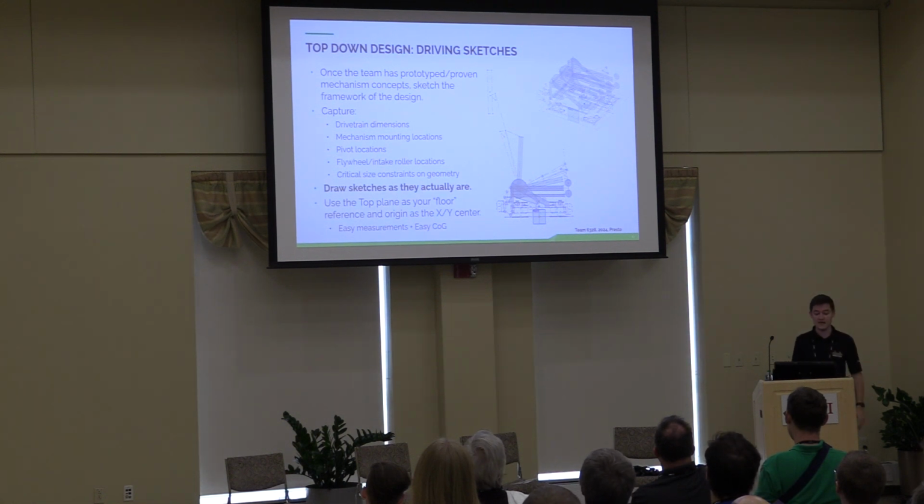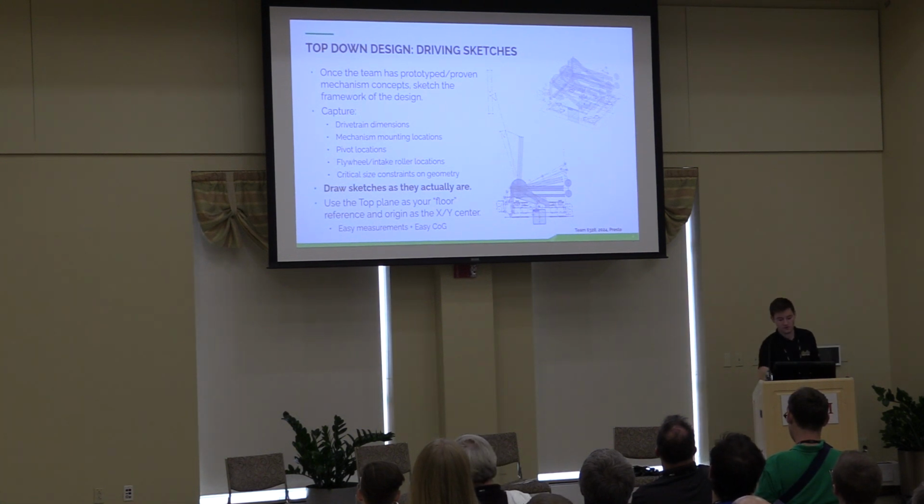I've actually started renaming it from top to floor, so you can just rename the default sketches, the default planes, and use that as the bottom. For example, you can see, and Susan did that as well, where their drivetrain tubes that they drew from the side are the correct distance from that floor plane. And they've also got it centered about the origin.